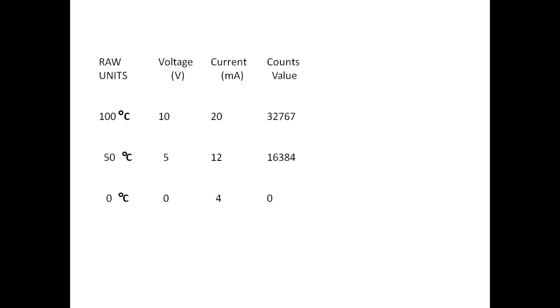Now this is converted by the A to D converter to a value from 0 to 32767. This is coming at your channel, at your input. We give an input address for each input of the module, so for each channel you get this range, 0 to 32767 for 0 to 10 volts.